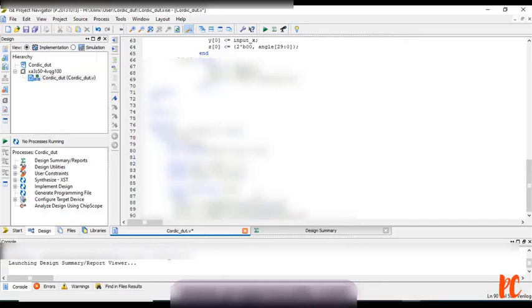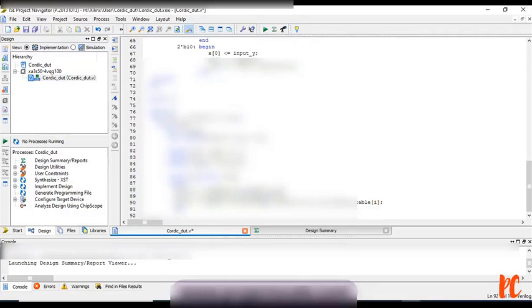If it is wrong, I mean if it is false, then we will be going for z of I minus arc tangent underscore table of I. So this condition needs to get satisfied. Let me end it with end module followed by end. Let me end this whole thing with end followed by end generate.